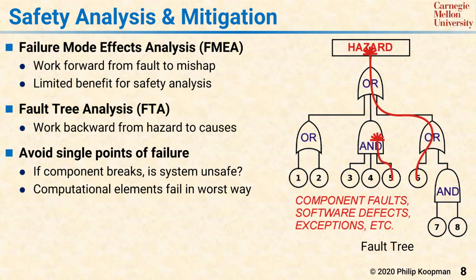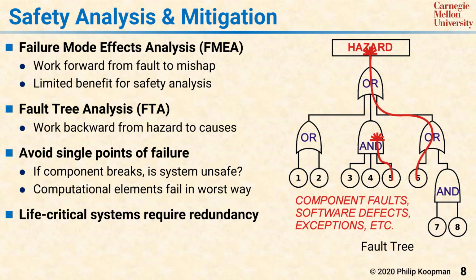For our vehicle speed control example, any single computer in the system must be presumed to fail, for example, commanding full engine power, which is unsafe. That's why a safe engine controller has two computers working in tandem, so that if one of them fails, the other can at least perform a system shutdown.